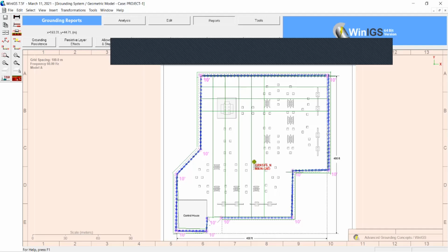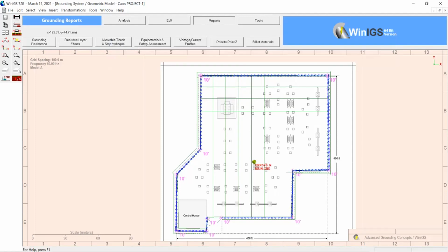We have to use them. So what is important for us? First of all, the important thing is ground resistance, for the system you created using ground conductor, fence and ground rod, and inputting the soil data.